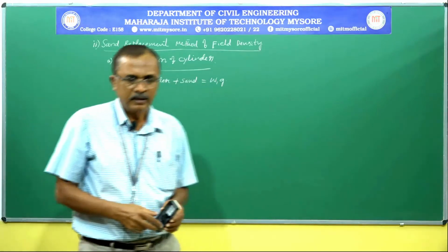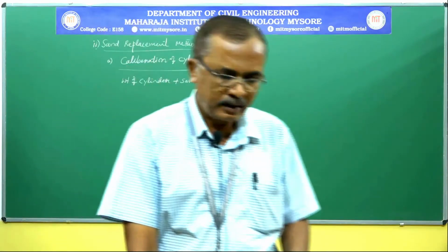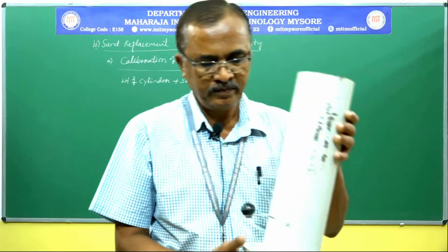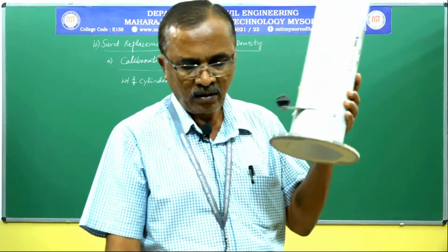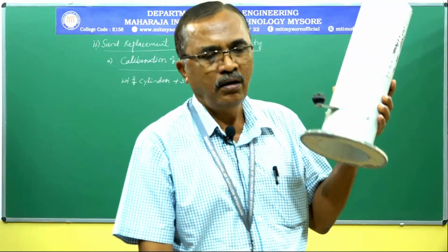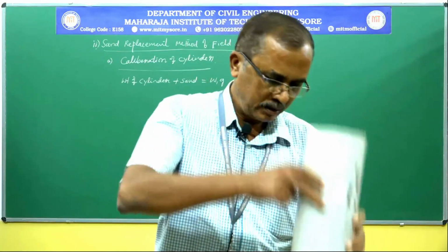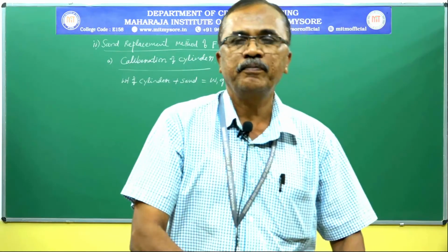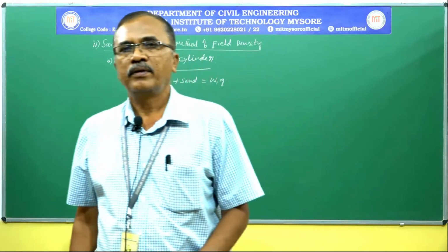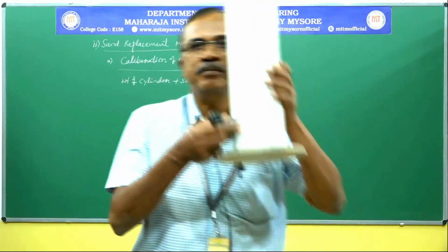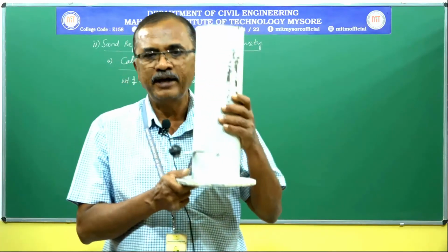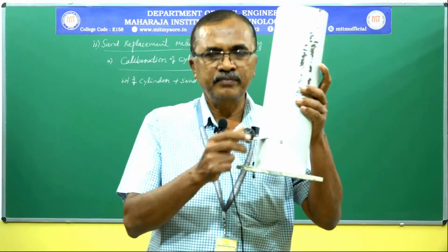Next, place this sand pouring cylinder with sand on the glass plate or a paper, open the shutter.